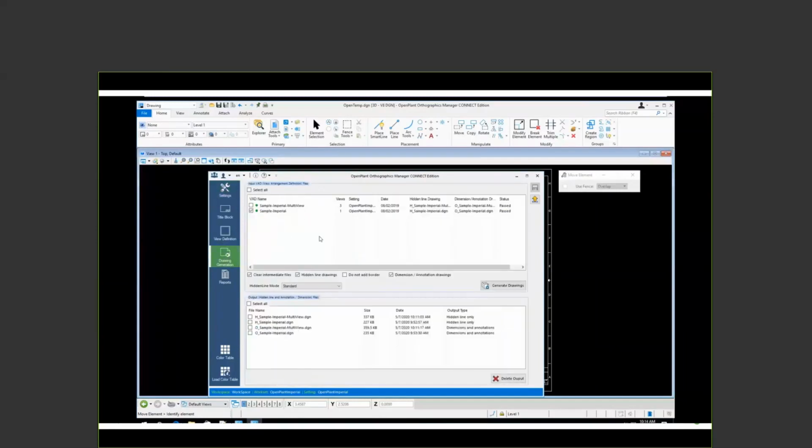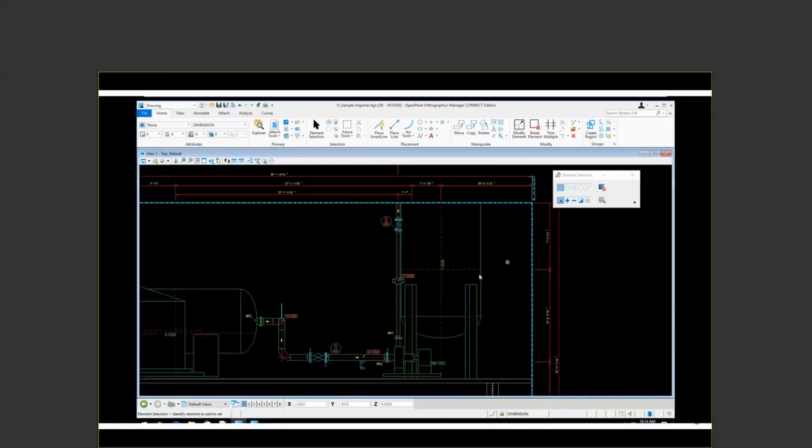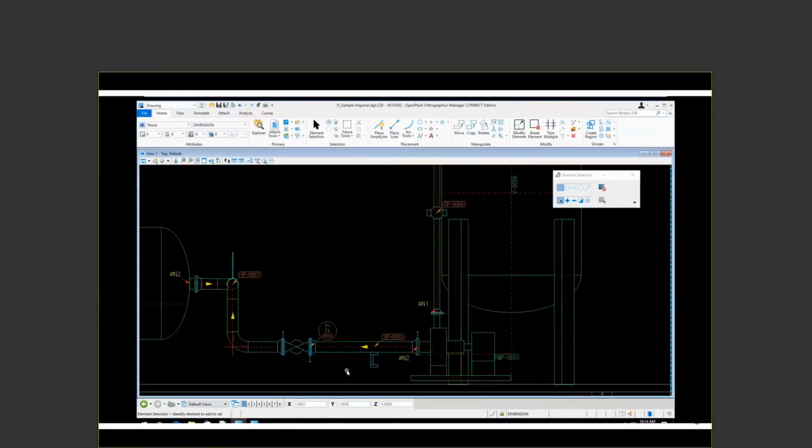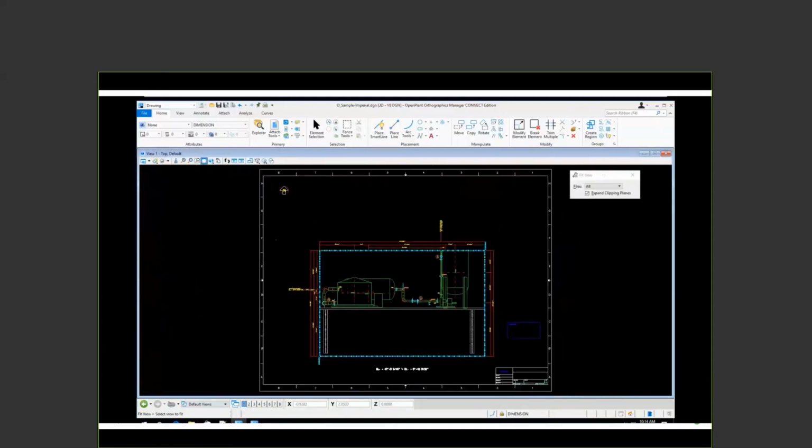go into your drawing generation and simply just generate the drawings. And what that does in the background there, it actually processes the drawing, and I'll show one here in a second when it's complete. So it automatically creates the extracted ortho from that particular view that you set up. It'll auto label, auto dimension, auto annotate nozzles, valve labels, anything else that you set up into there.